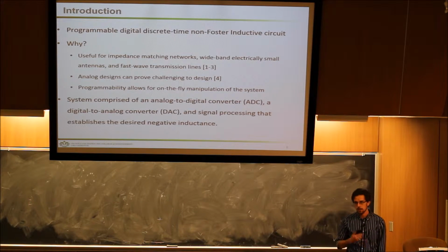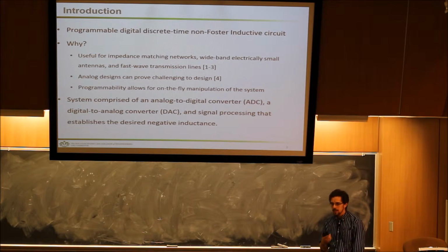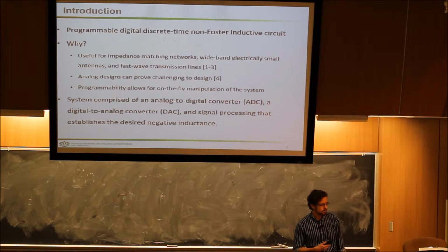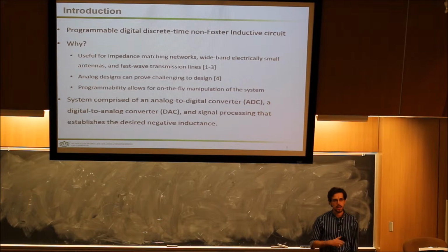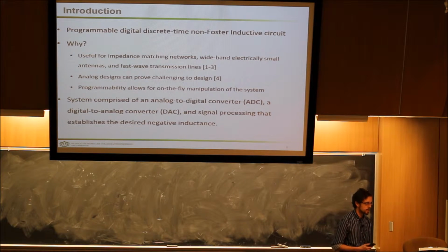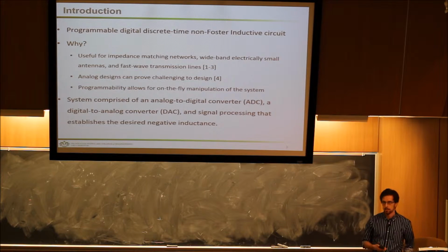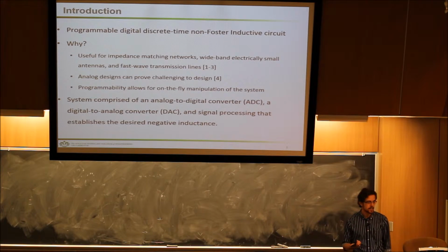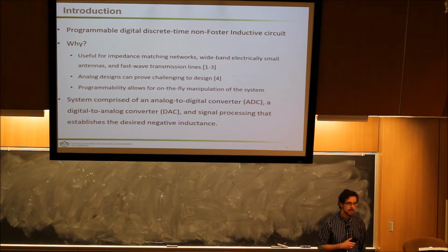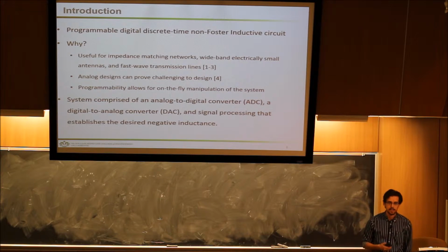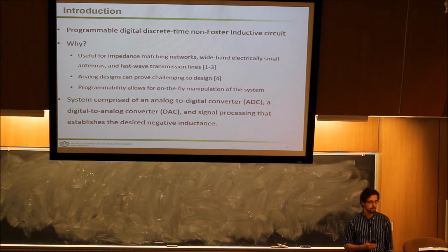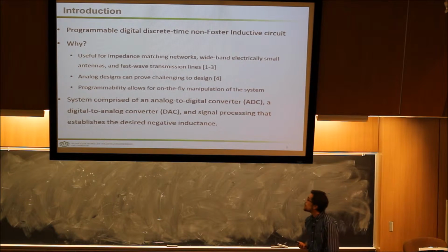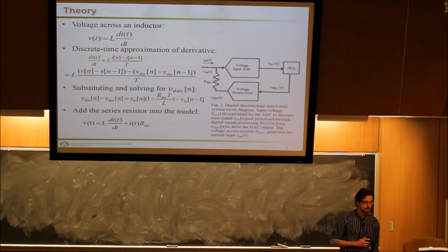We decided to do this because even though you can do this in an analog sense, making these in an analog fashion, as will be shown, is actually quite difficult, and the difficulty arises in the stability of that. And as I said before, since it's programmable on the fly, they can change it anytime that they want. So even though it doesn't follow the traditional one block, two block, three block schematic, an ADC, a DAC, and signal processing, it still fits under the purview of what everyone would want. Also with this, we can have a negative inductance, which, I thought, is a little bit cool at least.